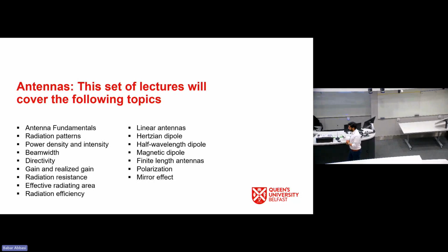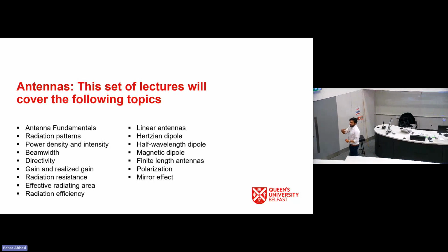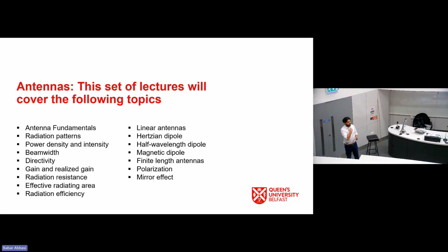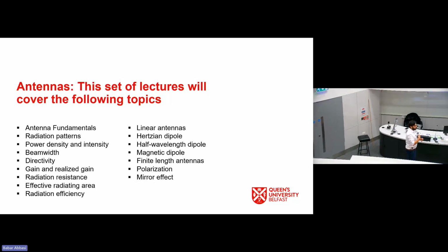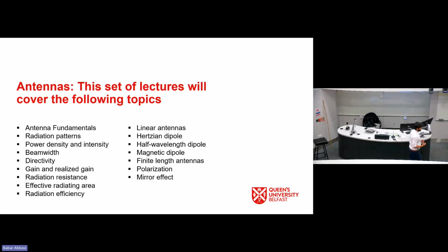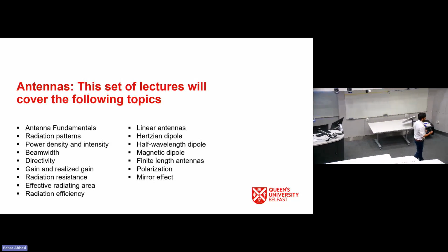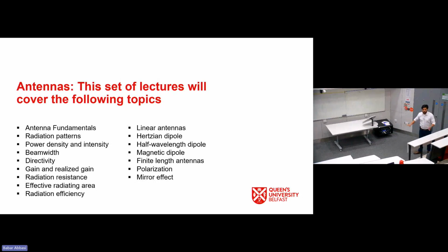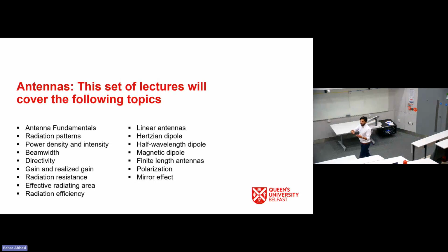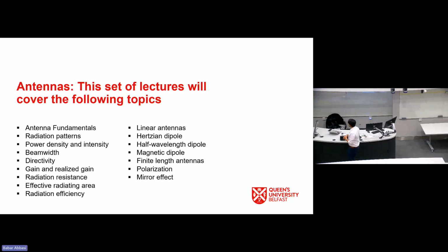in some particular applications. For example, if we have an implantable antenna, an antenna placed inside the human body, wanting to communicate with an antenna outside the human body, then of course it's an extremely harsh environment, and antenna radiation efficiency will decay significantly. So we are okay if the antenna is operating at more than like 30% efficiency. We just want it to throw enough energy outside so that we can read what's going on inside the human body.